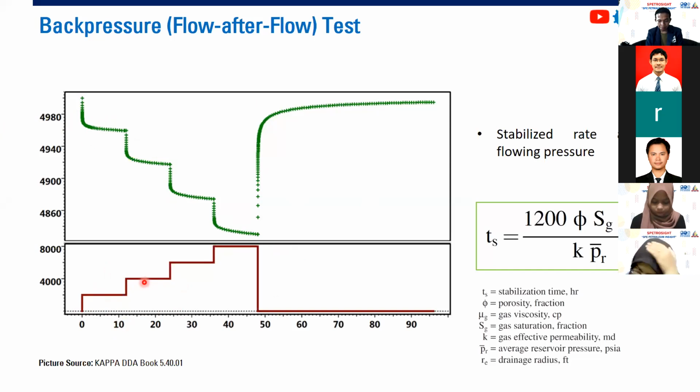We have this Q2. Again, increase the choke, and then finally we get the fourth data. You do this by well testing, but the condition is that the stabilized rate and stabilized flowing pressure have to be reached. Which means that the well should reach or approximate the pseudo steady state condition. We cannot do transient regime here. We need to achieve pseudo steady state regime.